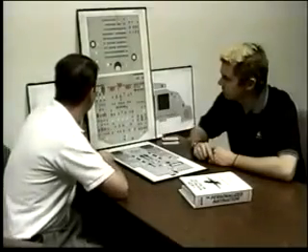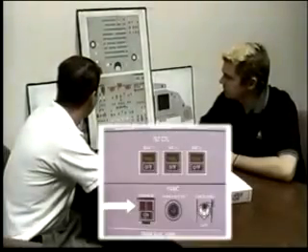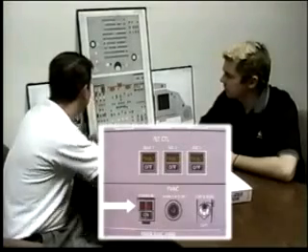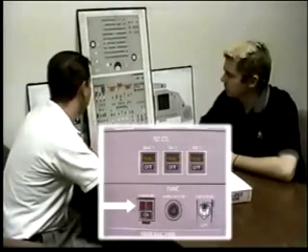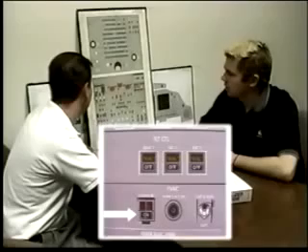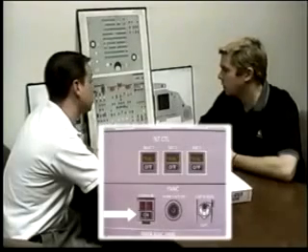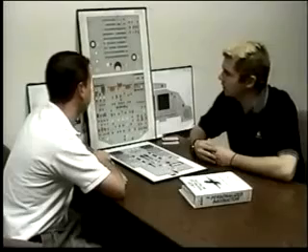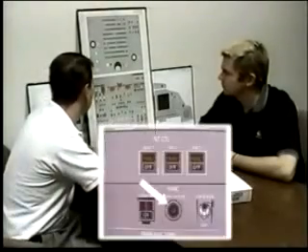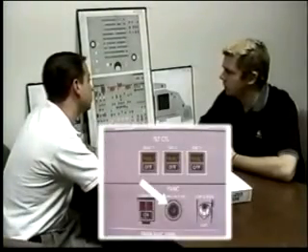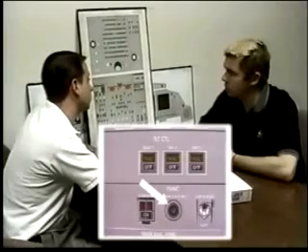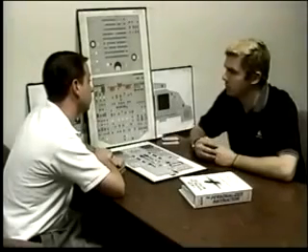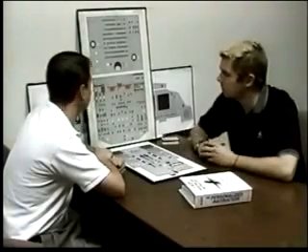EVAC. You have a red EVAC on the command button. Describe to me what this command button, what the EVAC means, or selecting the on. EVAC means that an evacuation has been commanded. On indicates that I've selected it from the cockpit. What about this horn shutoff? That just means that if an evac is being commanded, either from the front or the back, I want to silence the horn from the cockpit. Only the cockpit horn, though.